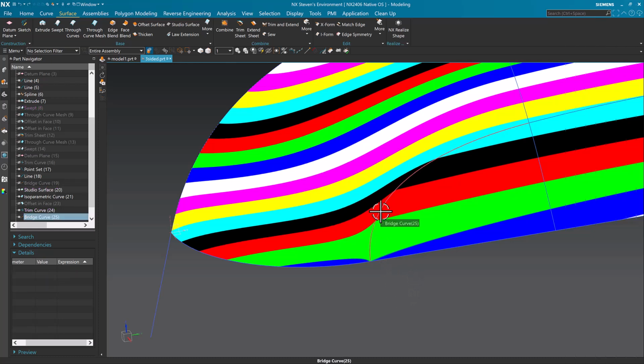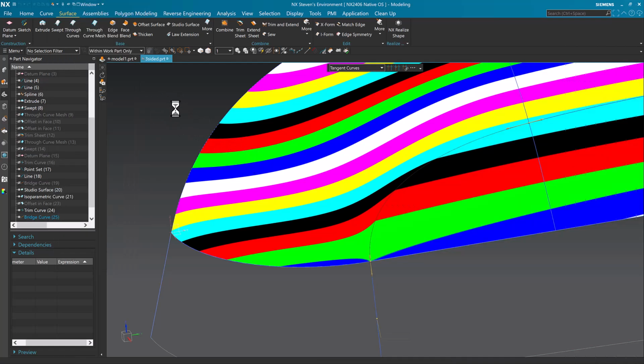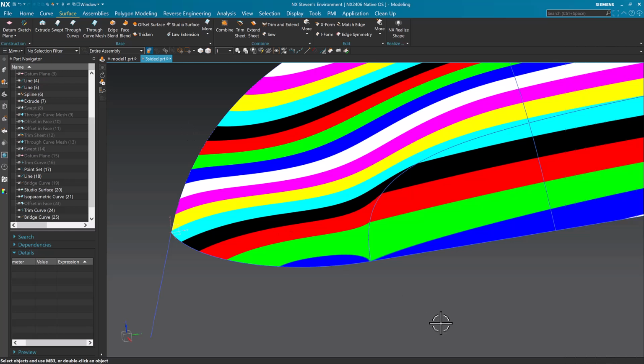Okay, there may be cause for me to double click on that and go, well, you know what, maybe I want to change this from G0 or G1 to G2 and see if that does anything for me. And right, it just kind of pushed that error out a little bit. And again, I expected to see that. And again, the reason why is this is an arc going into a line. This is a line coming down.